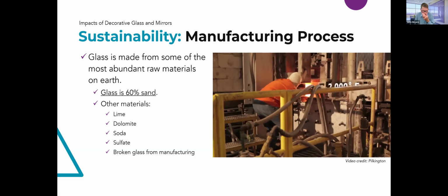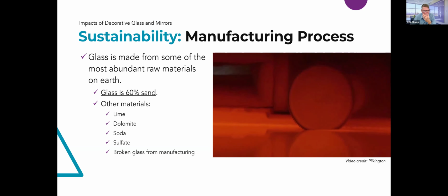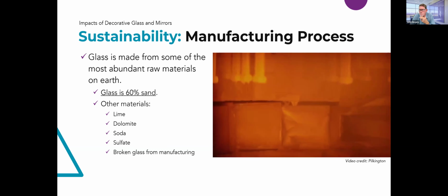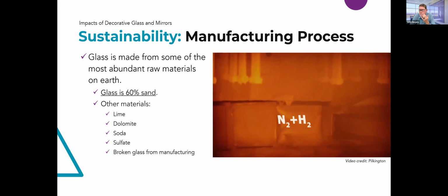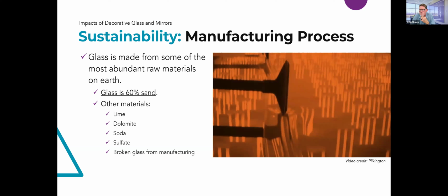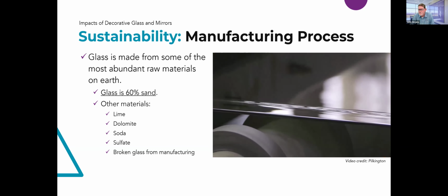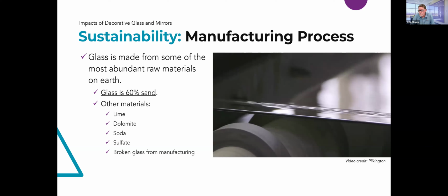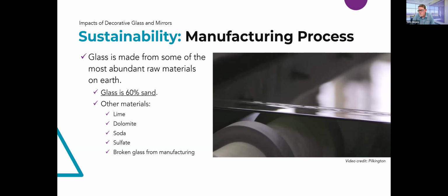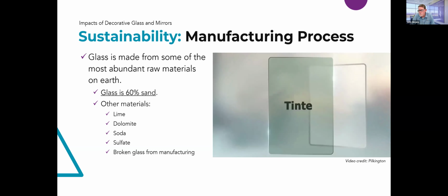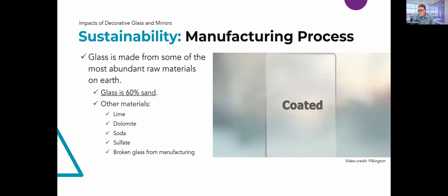The glass is made thicker by confining its initial outward spread over the tin. To make thinner glass, the top rollers controlling the width of the glass are sped up to produce a gentle stretching action. A controlled atmosphere of hydrogen and nitrogen within the bath prevents the tin from oxidizing. When it emerges from the tin bath, the glass is sufficiently hard so as not to be marked by the conveyor rollers. The float glass manufacturing process can produce clear, tinted, and coated glass products.